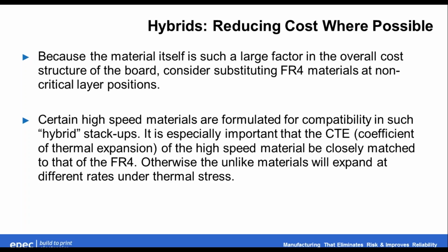It's especially important to know that the coefficient of thermal expansion of the high-speed material needs to be closely matched to that of the FR4. Otherwise, the unlike materials will expand at different rates under thermal stress, and what happens then is your plated through hole interconnections can get pulled apart after a couple of thermal cycles, and that's obviously a bad situation. So you do want to select your materials wisely.